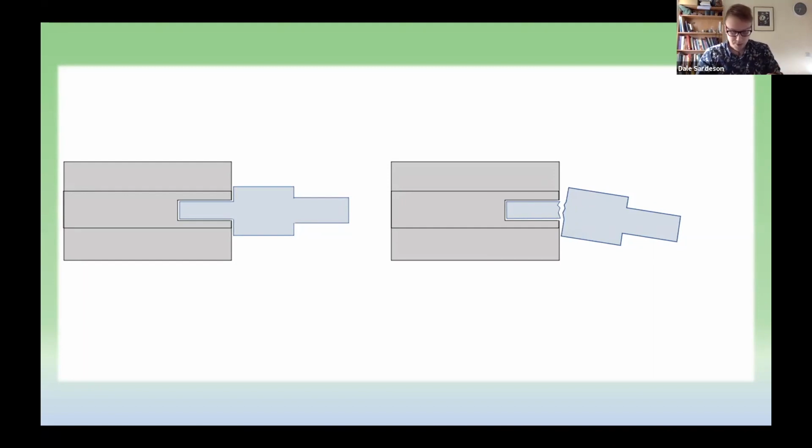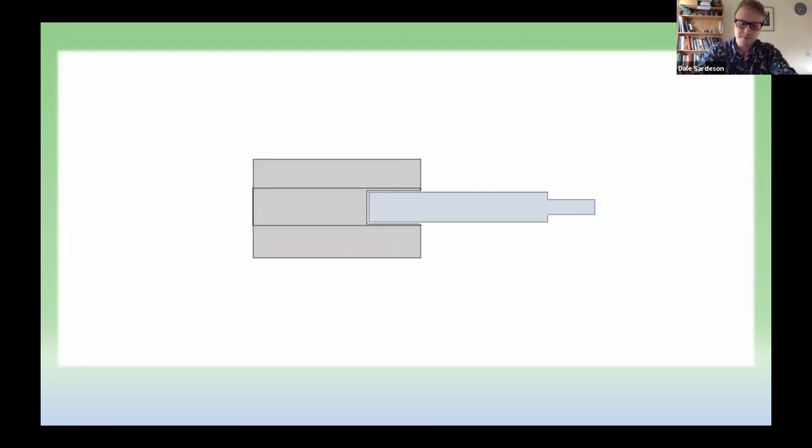By this point, the client was talking about whether or not the entire arbor itself ought to be replaced, especially considering the arbor was bent as well and there was some wear in the pinion. But I felt certain that we didn't need to lose the whole original arbor. So I drilled out the hole as big as I dare, which was a 2mm diameter hole, and rather than fit an extension with that angular weak point, I just fit a straight piece of bar with a pivot turned on the end. This meant that the new extension was no longer quite at the original diameter of the arbor, so it was an aesthetic compromise made for an improvement in strength.